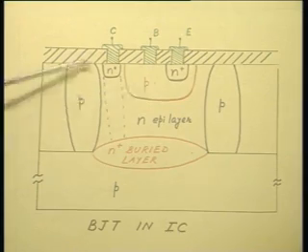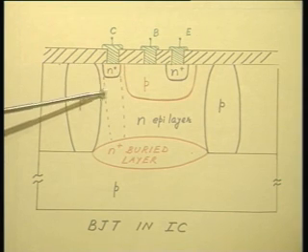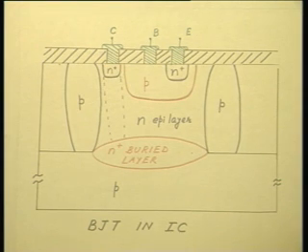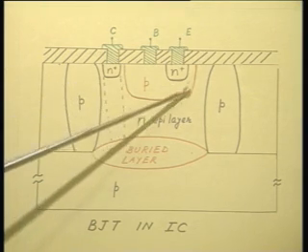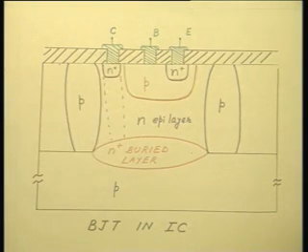How can you suppress it? By suppressing its gain. How do you suppress its gain? By increasing the base width. This is a lateral transistor PNP. So, this is its base, right. That means, the base of your actual transistor should be a considerable distance away from the isolation P tub in order to keep the base width of the parasitic PNP transistor large.